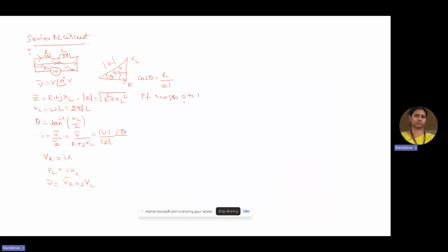When the power factor is closer to 1, it means that the transmission is efficient and the losses are less, and the power transmitted from the sending end is maximally reaching the receiving end. If the power factor is closer towards 0, then much of the power has been wasted in the losses and the transmission is not that efficient. So we always strive to improve the power factor.